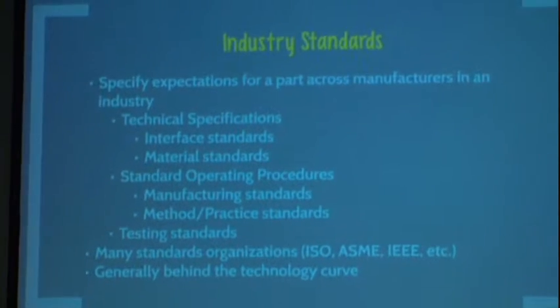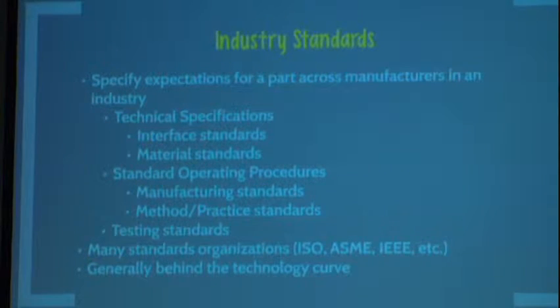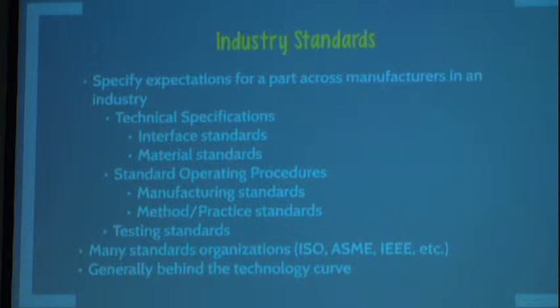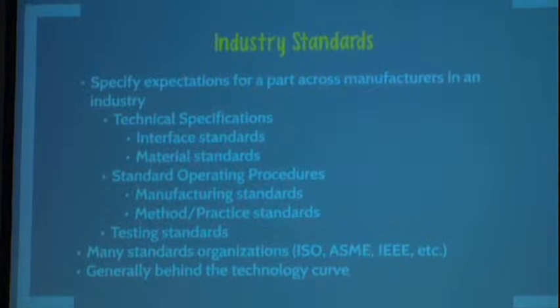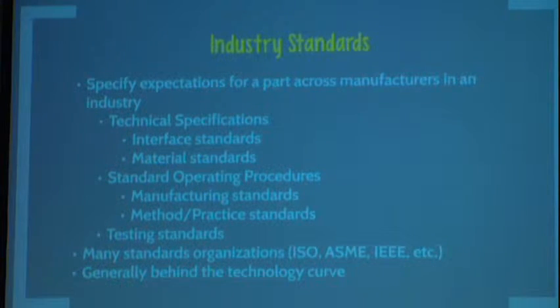And then the most common one that you'll interface with is the last one, testing standards. So this will be a standard that says if you are building something, here is the test that you run, right? So if you're building this chair, right, it's going to tell you this chair needs to support a still load of 350 pounds. And this chair needs to be able to support a dynamic load hitting it at 3 miles an hour of 290 pounds, something like that. Or it'll give you a fatigue test and tell you how to run it. So those are the kind of standards that you'll run into a lot. And as you design devices, you'll get into that.